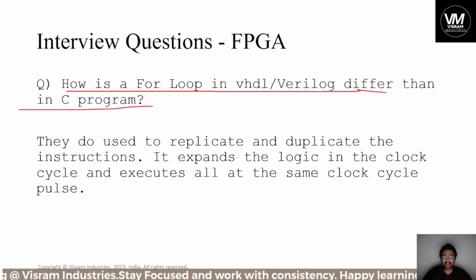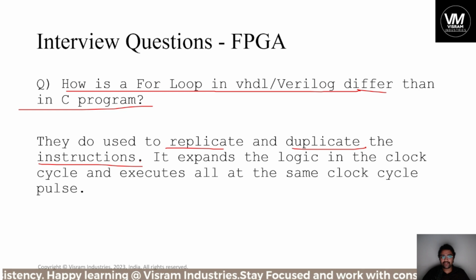In FPGA development in Verilog, the only synthesizable constructs are if, else, or case statements. The remaining for loop, repeat loop, and while loop are generally non-synthesizable, and those are used only to replicate or duplicate the instruction sets, not for repetition, like printing the data n number of times. A for loop is not used in Verilog HDL or VHDL for printing the data that many times. Those are only used for replicating or duplicating the instructions.